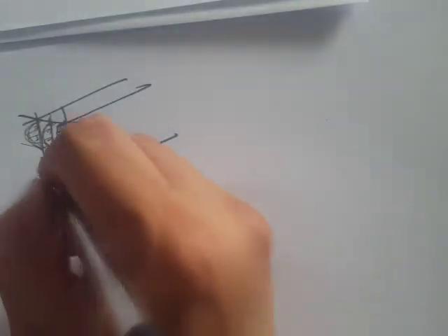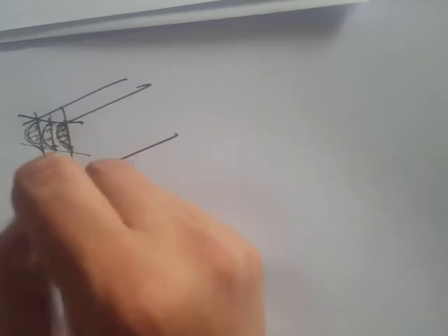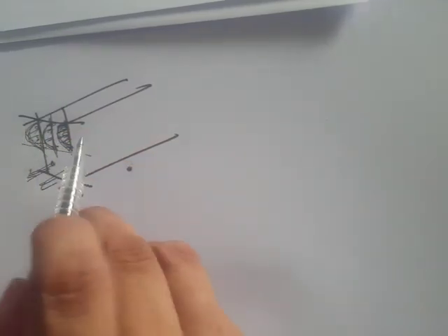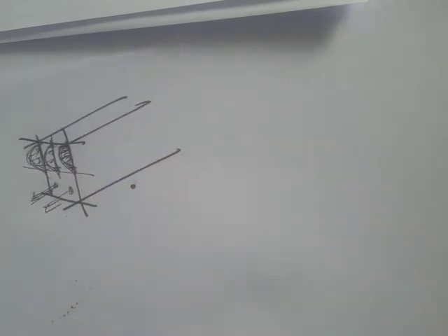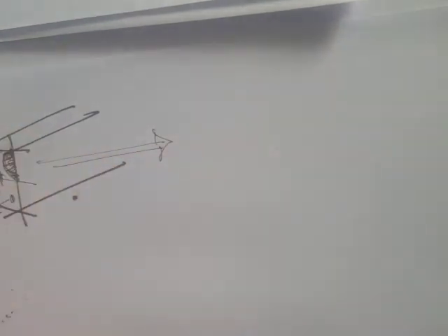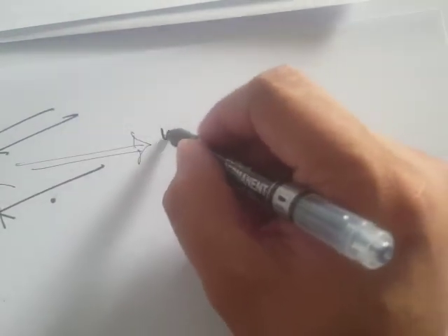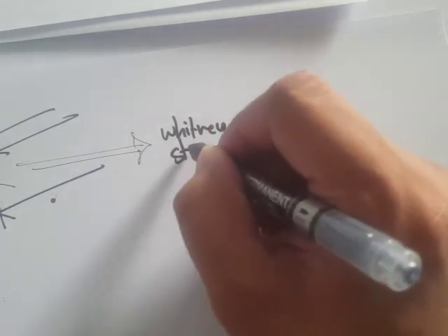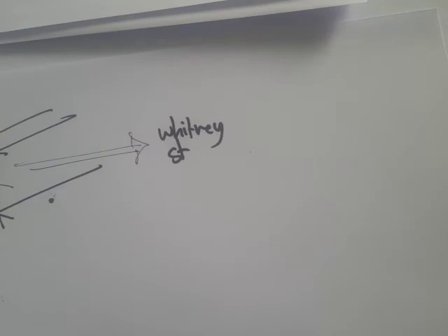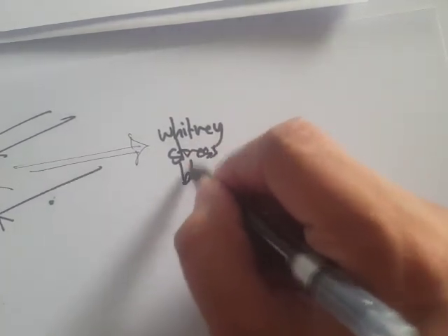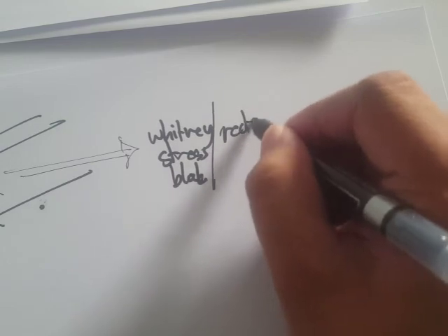But if we have this non-uniform, parabolic stress block, then that's going to be difficult for computations. So there is a way to transpose this parabolic stress distribution into an easier, handy way for calculations, and that's what they call the Whitney stress block.